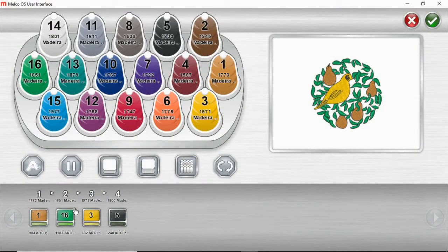Lastly, if you have a design that just has 2 colors over and over again, you can always drag this recursive down onto one of those. If you want to get rid of this, you can just drag it off. And then let's take this back to the way that it was. Select the color, select the cone of thread I want on it. Color change down here, cone of thread up here.